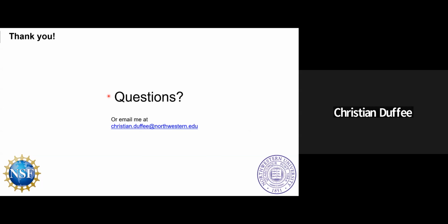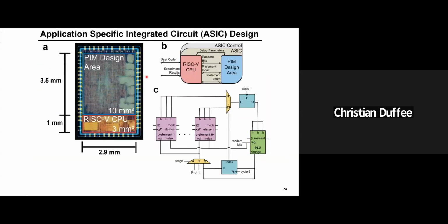Thank you. Very nice work. When you do the ASIC, which part is delegated to the outside, or is the whole pipeline implemented in the ASIC? Yes, so when we are running an ASIC problem, we write C code that runs on the RISC-V CPU. But all the C code does is initialize our initial temperature, our ending temperature, and the sweep parameters. Everything runs on our design up here. Yes, it is fully digital.